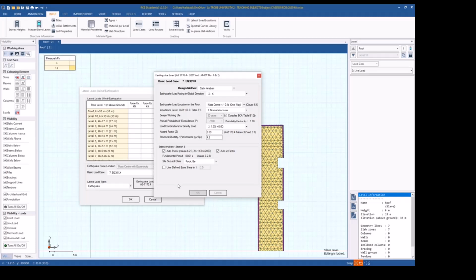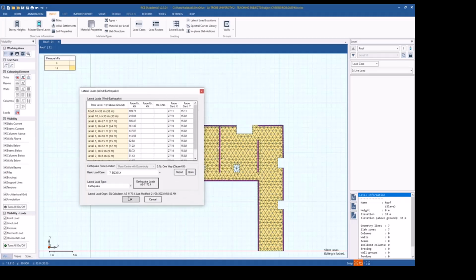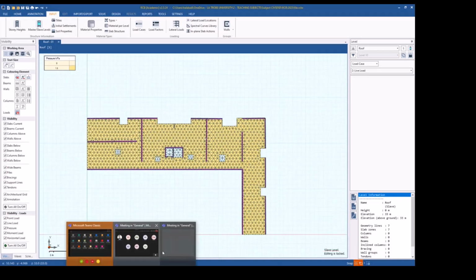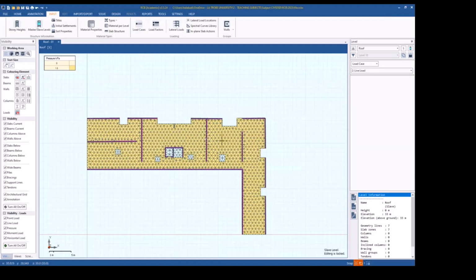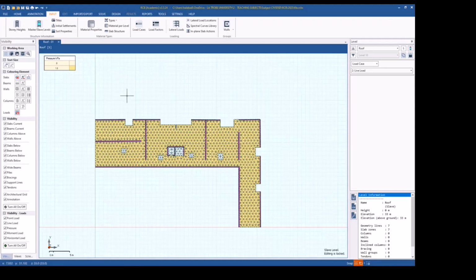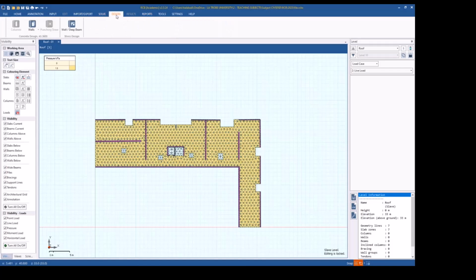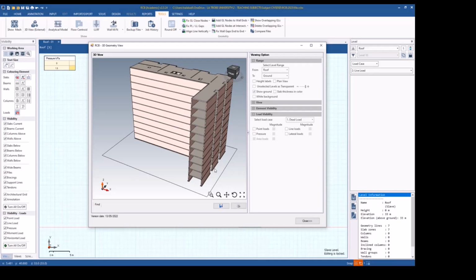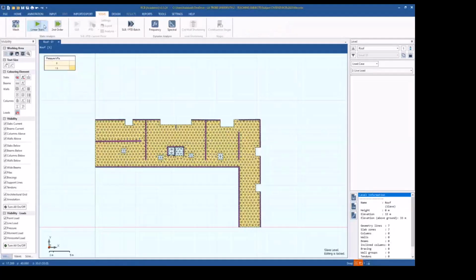Say okay, and by now all your lateral loads are defined. Let's see, is there a question? No. So far we should be ready. We have defined the structure, and we have defined the loadings, whether vertical loads or lateral loads. After this, I think we're all good. The loadings won't appear here. Run the analysis: go to solve, and click solve linear. That should give you the stress calculations.